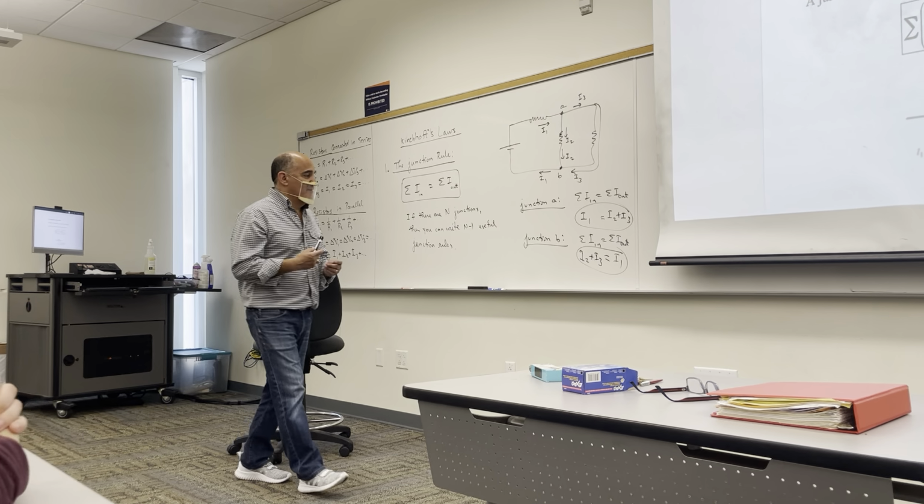We can still combine them even though they're surrounding batteries. Well, because they're on the same line, so they'll have the same current. They're in series if they have the same current. So this one will have the same current as that one, and this one will have the same current as that one because they're on the same line. If you have one amp over here, that one amp has to make it through that one because there's no split. Right.